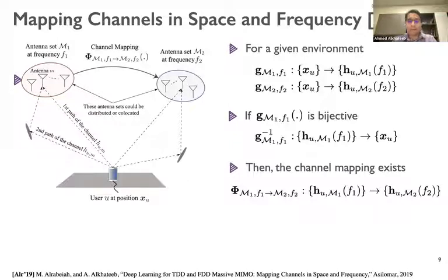If we guarantee that this condition is satisfied, which in practice it is with high probability if we have a relatively reasonable number of antennas, I think 6 or 8 antennas in a reasonable communication environment. And of course, it depends on how many multipaths we have, what the geometry of this antenna array is, the frequency band, etc. There are some papers that justify and go over this condition in detail. But the observation is that in classical and typical wireless communication environments, this condition will likely be satisfied with high probability, at least.